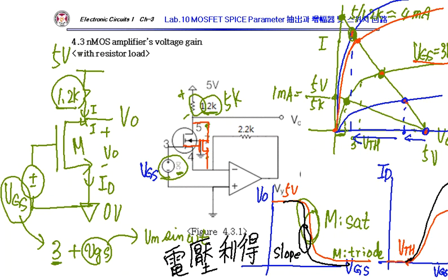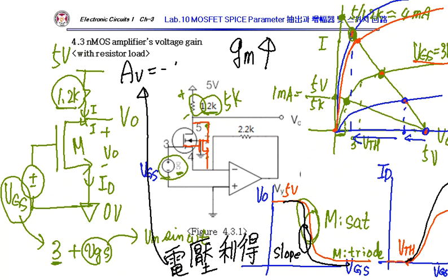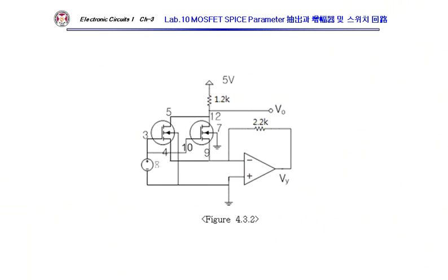So if I increase the transistor count to 2, my GM will increase twice. And then here, see my voltage gain. If I increase the transistor to 2, my GM becomes twice. Voltage gain will be almost twice. Yeah, here it shows the one.